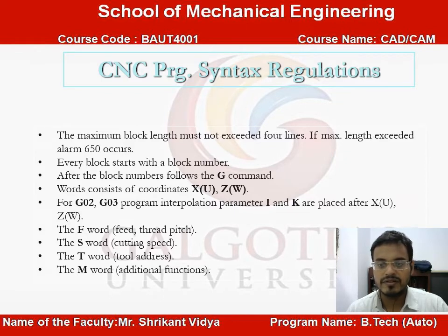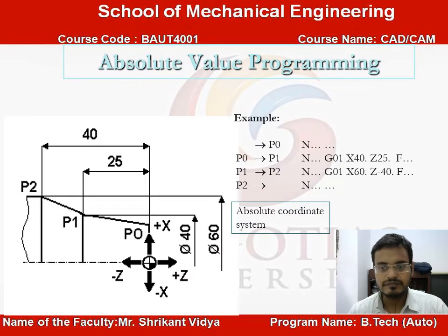The F word means feed or thread pitch. The S word means cutting speed or spindle speed. The T word means tool address. The M word means additional functions. So you can see the diagram. The absolute system is represented here. Absolute value programming we have already discussed in the previous lectures.